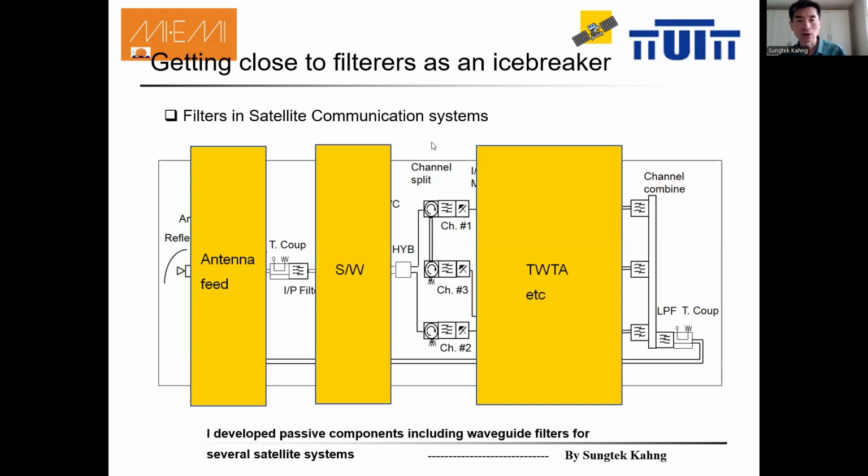As was mentioned earlier, the two paths are the TX path and the reception path. So the antenna is shared by the paths. For the reception path, or path of the RX, you see a coupler and input filter, and the input filter accepts the radio frequency of a wideband, and it should be divided into different channels.